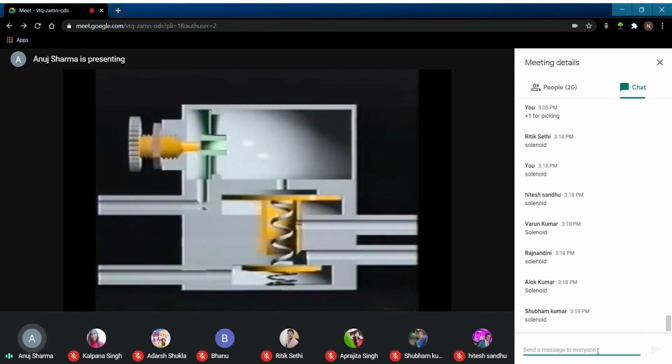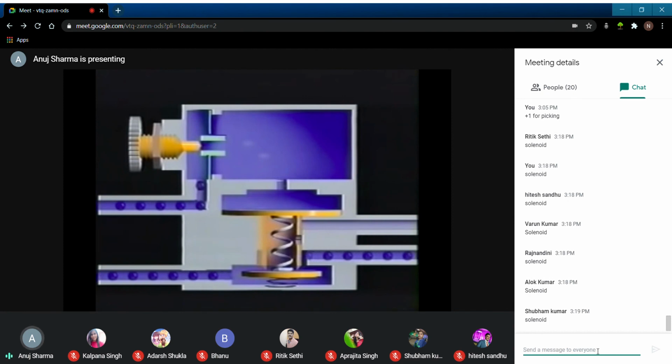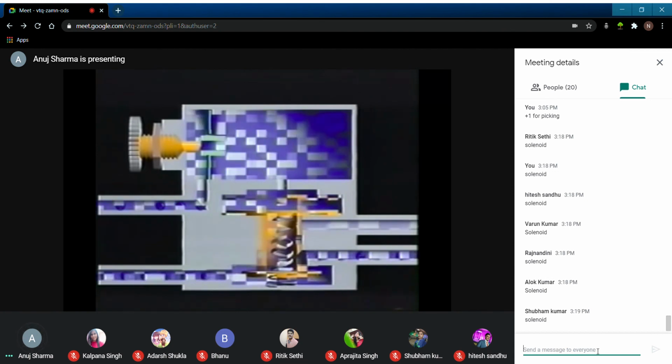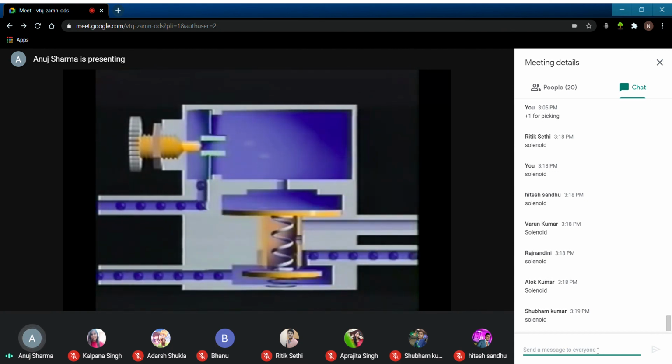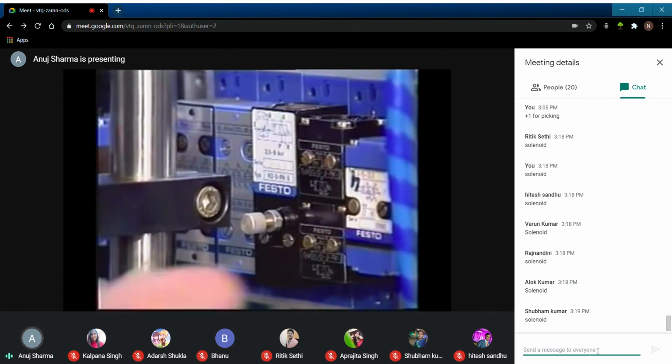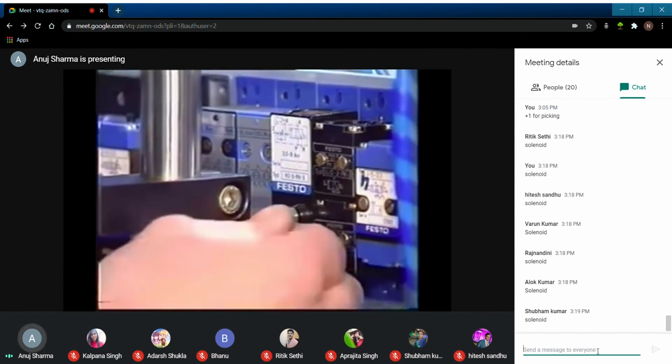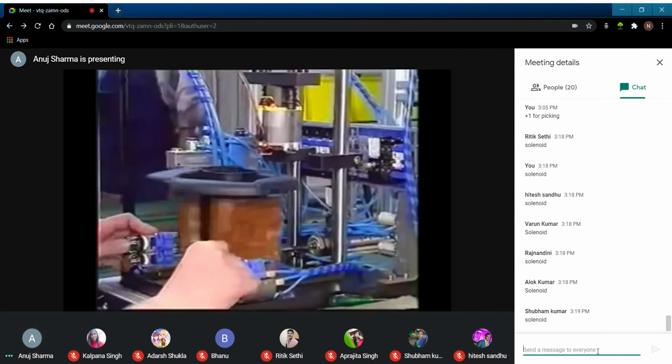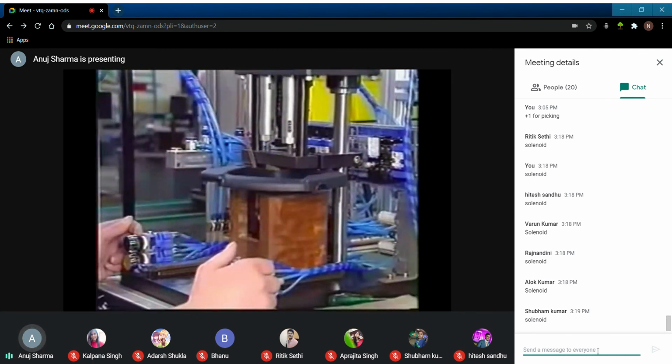Another type of combination valve is the time delay. It contains a one-way flow control valve, air reservoir, and directional control valve. This valve delays the sending of a signal for a set time. The length of the time delay is controlled by adjusting the rate at which air is allowed to enter the reservoir through a flow control. Once the reservoir is filled, the directional control valve shifts, allowing the signal to continue through the circuit. In this application, the time delay valve holds the cylinder in position for a few seconds to ensure that the screw is fully seated in the hole.